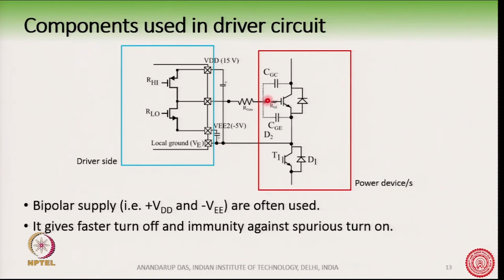So, what we are trying to do here is charge these capacitors up. Now, we can charge this to 15 volt through the VDD of 15 volt, like this. The charging process will basically be controlled by this RC element here, and this will turn on the IGBT.